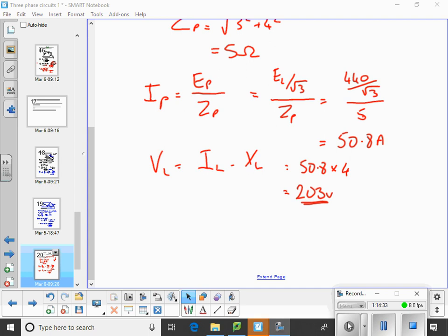Right. Now we'll be moving on sometimes later on to a module where we will be interested in the angles. But at this stage, I don't want to complicate it with that. Just the magnitude of that current and voltage. A lot of the time, all you want to know is how many amps are flowing or going to flow, so I can put the right circuit breaker, the right cable in. The phase relationships aren't of interest then, in other times they are of interest. All right?